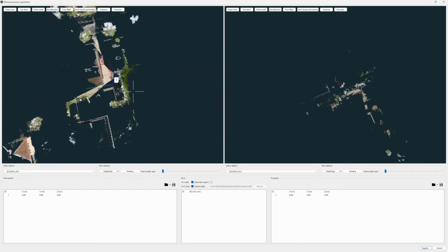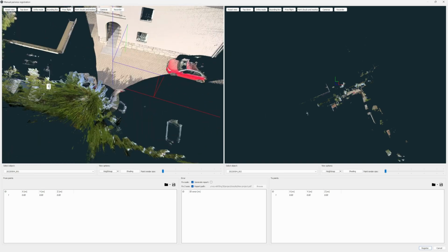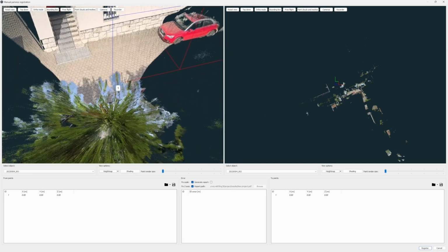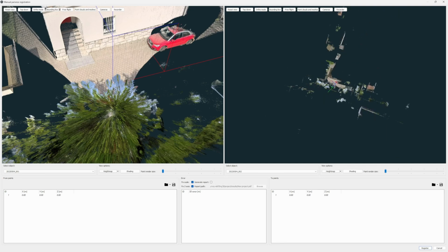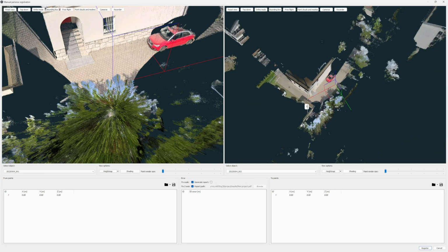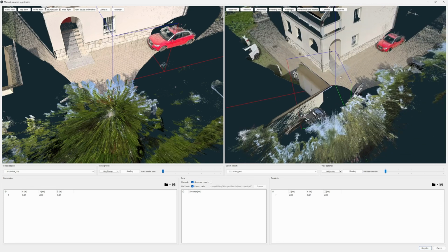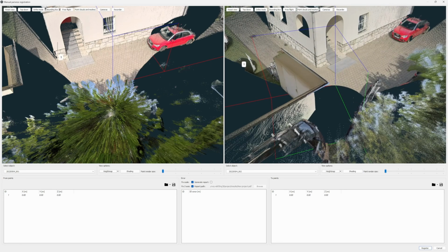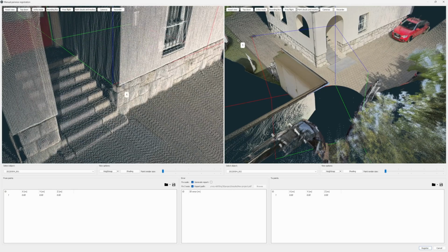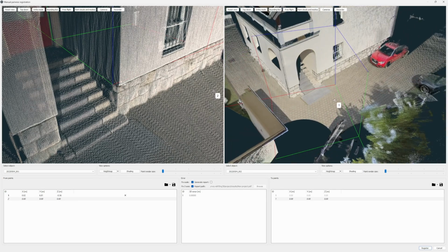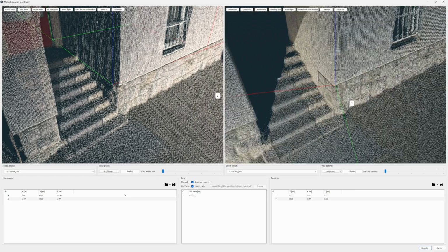First, zoom to the vantage point of your point cloud, so you see what you saw from the standing point. Do this for both point clouds. The alignment works on a set of identical points, so you have to find at least 3 points that are common to both point clouds. A pretty easy and obvious choice would be this corner. Mark it on both point clouds.